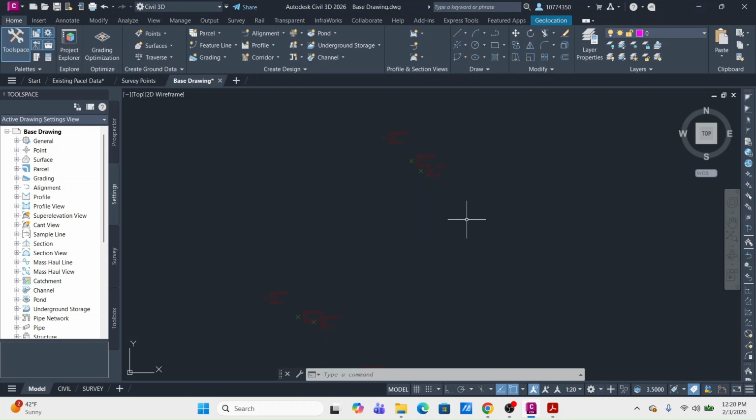Alright, so let's begin drawing up our existing conditions. With the survey points that you've imported, this is as simple as playing connect the dots. That's all we need to do. To start doing this, I think we need to go over the difference between a line and a polyline. For surveying, and just in general, you want to use polylines. A polyline is a connected line that is made up of multiple segments, and it acts as a singular object.